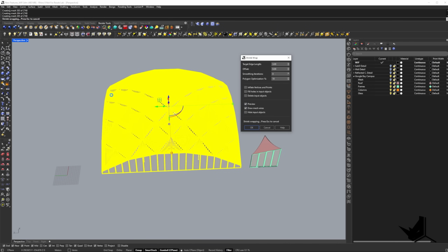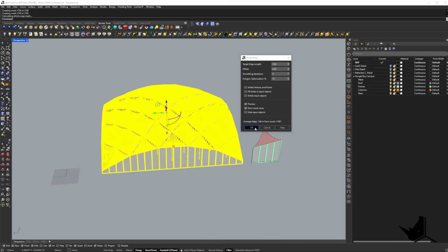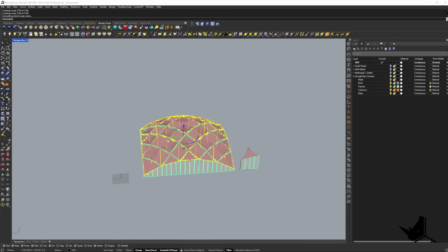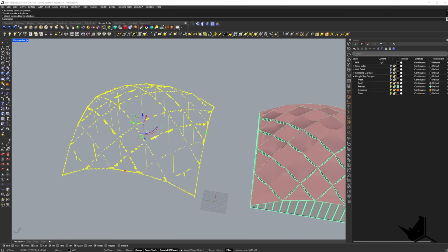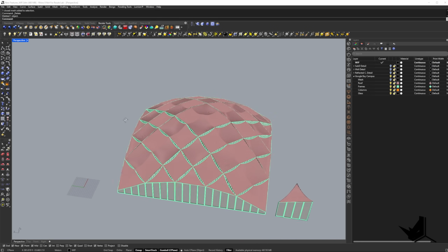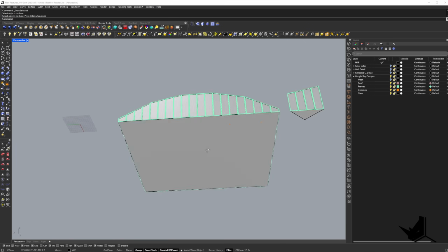When you click the preview, it's gonna calculate, it's gonna create the mesh, and you'll be able to see the final results. So for example, right now, you can see here the face count is almost 11,000 polygons. And when I click OK, you will see that I got a mesh which is totally messed up. This is unusable. So that's why we would need to use this surface as a bottom.